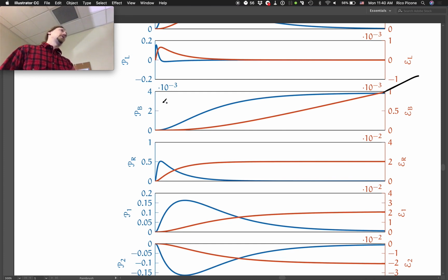It's going relatively slowly. We only put 1 volt in, so this thing is not going super fast, right? It's pretty slow. But then P_R, the power that the resistor is dissipating, peaks out here at 0.5, which is way bigger than the damper peaks out. But what's nice is that it goes away, right? As you speed up, remember the torque that you're applying is reducing, and so is the current that's flowing. So your I squared R drops off significantly, and you end up dissipating very little power in your resistor later on.